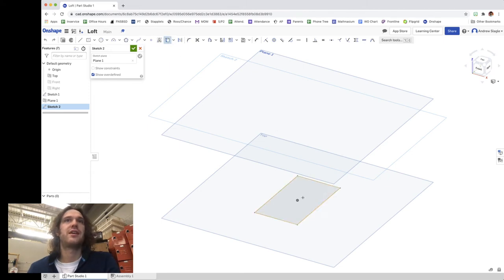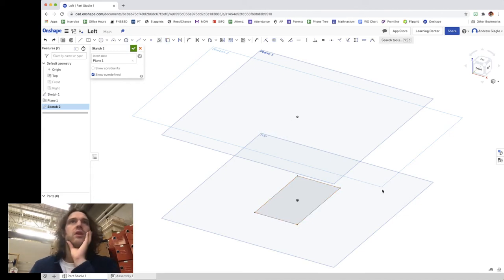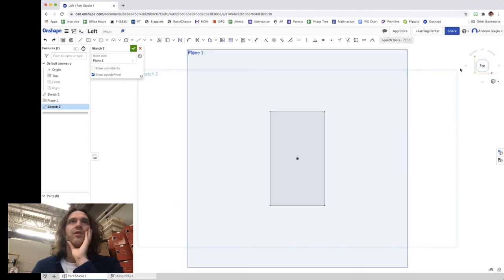What it does is it takes anything you want from the bottom sketch and copies it up onto the top sketch. Now I'm going to draw a pentagon that is centered on the same location, so I'm going to copy this point up to my top sketch. But really, you could copy any feature. You could click on any of these points, and those things would appear in my top sketch. Okay, so we'll get rid of that line. But that's how that works. Project Geometry. Very, very useful tool.